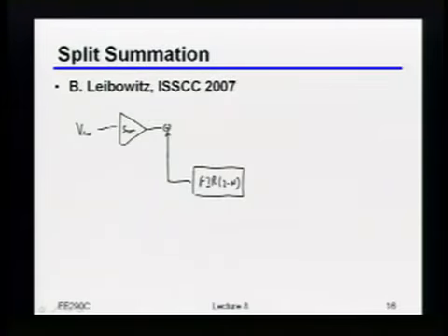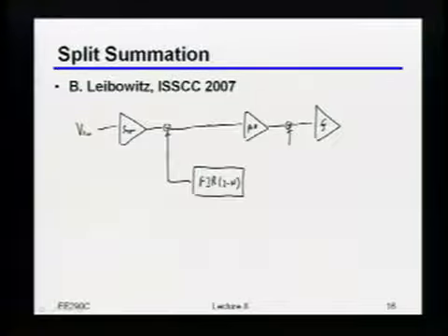And you'll see why I labeled this in a slightly funny way in 1 second. But just for the very first tap, because in the preamp I know that I maybe am only dealing with that one tap and maybe with offset, it's going to be easier for me to get a very, very high speed time constant, okay, a very small time constant.